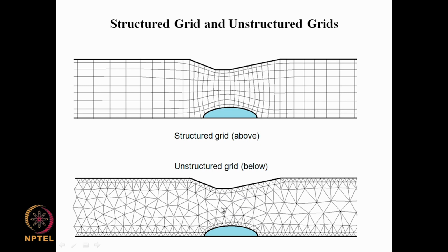So in that sense, the number of neighbors is not fixed in this unstructured grid. But whether you do the discretization on the structured grid or on the unstructured grid, we still end up with an equation like A phi equal to b, which we have seen. Okay? And in the case of structured grid in 2D here, for the diffusion equation, for the Laplace or Poisson equation, we will have the 4 immediate neighbors. That is, for point ij, we have i plus 1 j, ij plus 1, ij minus 1, and i minus 1 j.